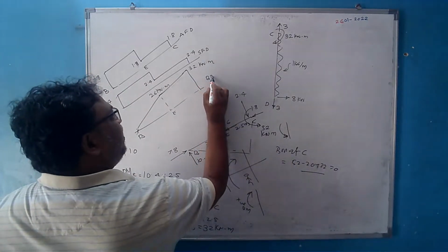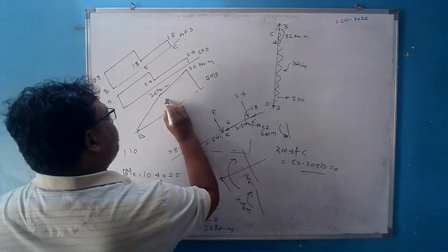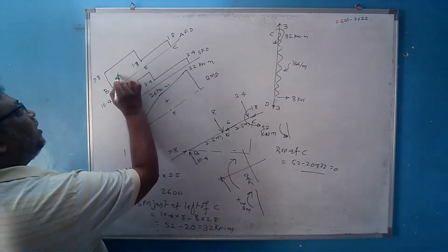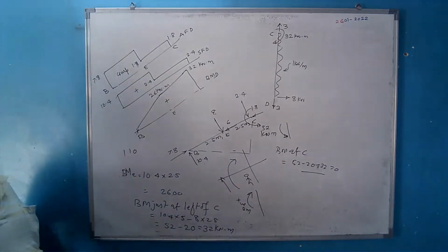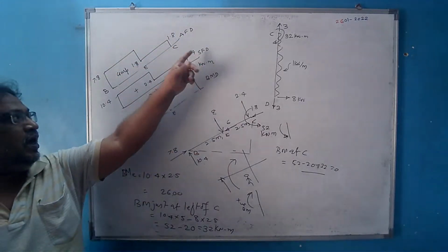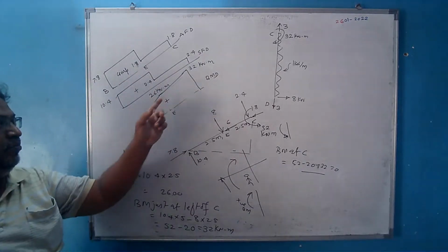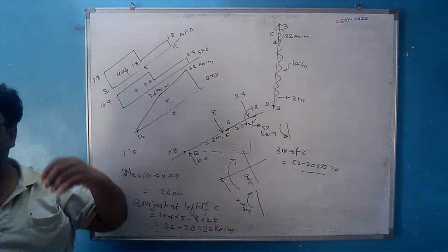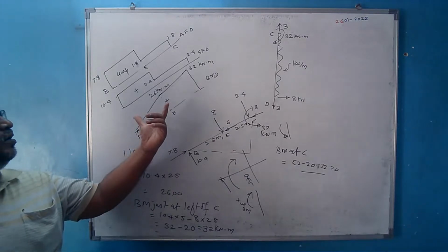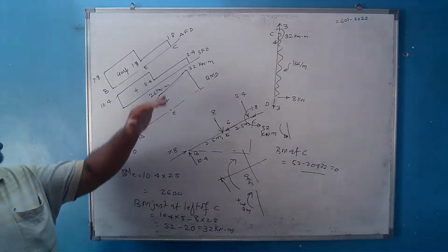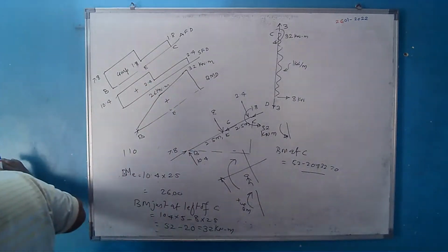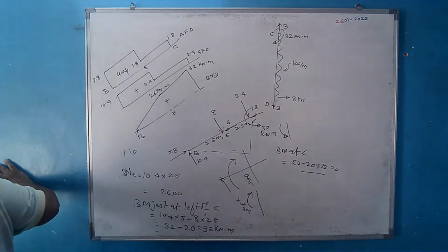This is the bending moment diagram and this entire diagram is positive, so this is sagging bending moment. This is positive shear force and this is compression. In the axial force diagram we have to write whether it is compression or tension. In the shear force diagram we write whether it is positive or negative. In the bending moment diagram also we write positive or negative. Positive indicates that it is sagging. Okay, fine. So this is how we can get the axial force, shear force and bending moment diagram for the second member. Is it okay?